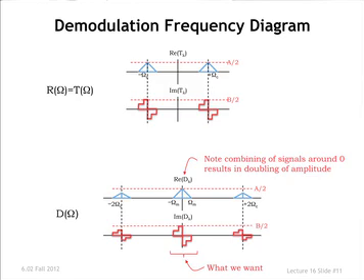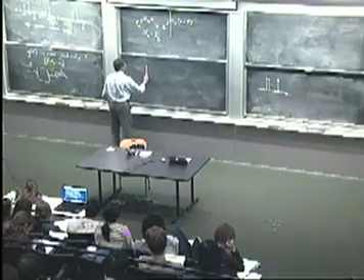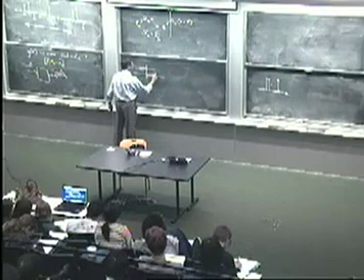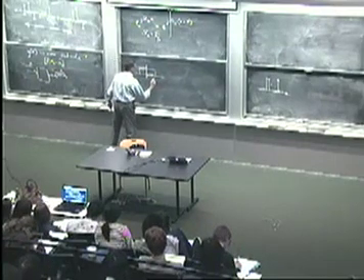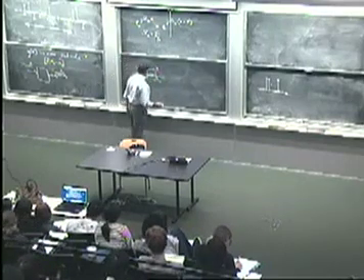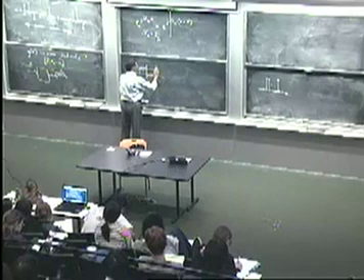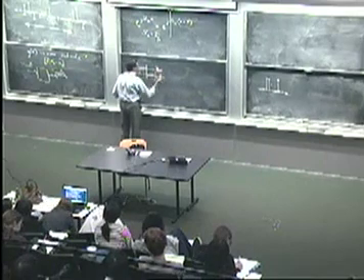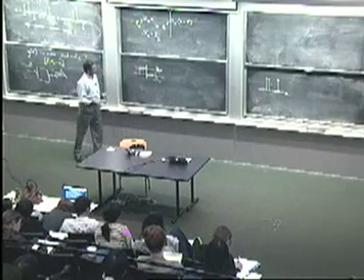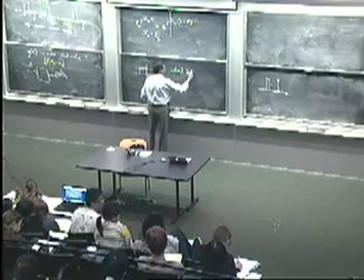Yeah. Low-pass filter. So, for instance, an ideal low-pass filter would be great, right? If you had a filter with a frequency domain characteristic that was perfectly flat in some region and then cut off, let me say it's some frequency omega naught. So something like that. Well, actually, we want a factor of 2 to compensate for the demodulation process if we want to get exactly the same thing back. So this would be in the frequency domain. Ideal low-pass filter.